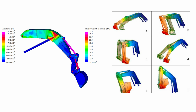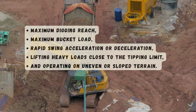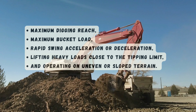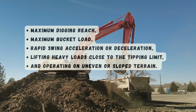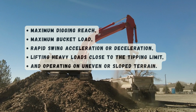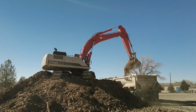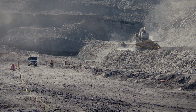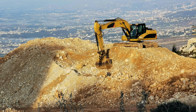with high accuracy. In addition to simulations, engineers perform load case studies that represent various extreme or critical working conditions the excavator may encounter. These load cases typically include scenarios such as maximum digging reach, maximum bucket load, rapid swing acceleration or deceleration, lifting heavy loads close to the tipping limit, and operating on uneven or sloped terrain. Each scenario is analyzed to understand how forces are distributed through the machine structure and how they affect stability and component stresses. Another important part of this analysis is the calculation of the stability margin, which indicates how close the excavator is to its tipping limit.